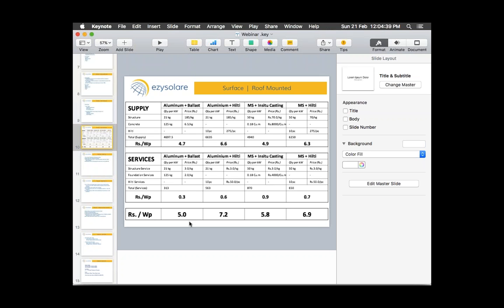So you're saying SS fasteners. And what is this about Dacromet fasteners? If you can explain to our audience, what are these fasteners? It's a normal fastener, a hot dip galvanized fastener only. It is given another Dacromet mechanical coating. Only one or two people are supplying them in the Indian market, and they have demonstrated that it is resistant to chemical impacts as good as SS.